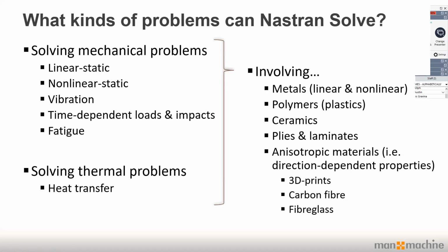Mainly for mechanical problems, you can deal with linear static problems, so metals at low displacements, nonlinear static, vibration. You can even have time-dependent loads and impacts. And we're going to see how we can use that to calculate plastic deformation later. You can also do things like fatigue calculations, and you can work out things like thermal expansion and heat-induced stress.